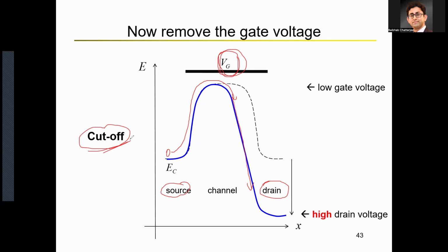So what we are learning here about MOSFETs is that they operate in different modes. They can operate in cutoff versus on, so that is off versus on, which is what, if you take a digital circuit course, is all you learn: that MOSFETs turn on and turn off. It's a switch, right? The MOSFETs do work as a switch. When the MOSFET is off, you're in the cutoff region. That is, you're applying a VGS for, let's say, NMOS, where your VGS is equal to 0. On the other hand, if you apply a positive VGS for your NMOS, then you're on, right? So that is on and off.